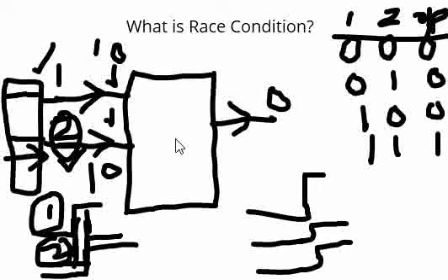So especially in high speed signals, what we do is length matching of these particular traces to ensure that we avoid these conditions. Even for low speed signals, we have to ensure that there isn't too much length variation from one signal to another, such that the small timing for which the output is not in a valid condition should not occur, right?